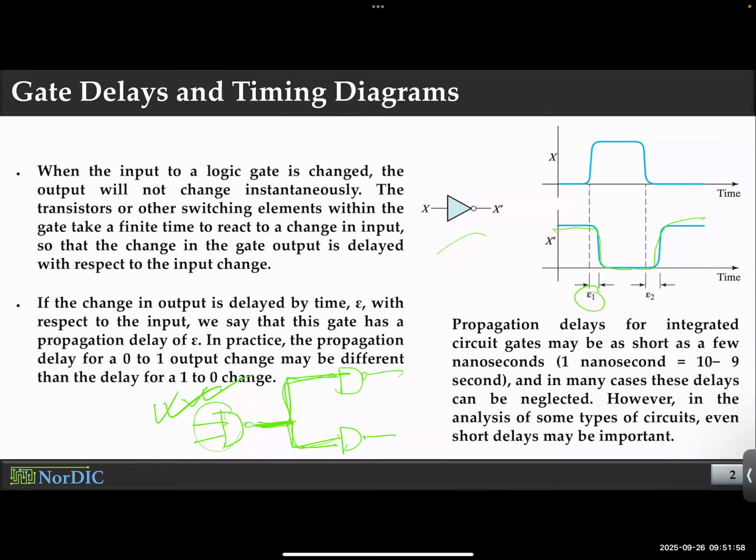Exactly the same situation. But remember, if you just stay with what we learned in the previous lecture that we just finished, you have an answer. Sharing with 10 components makes more sense. But what this lecture adds to the dynamics is that your fan out is 10 versus fan out 3. The higher the fan out, the higher the delay. The slower will be the operation. So can you live with this delay?